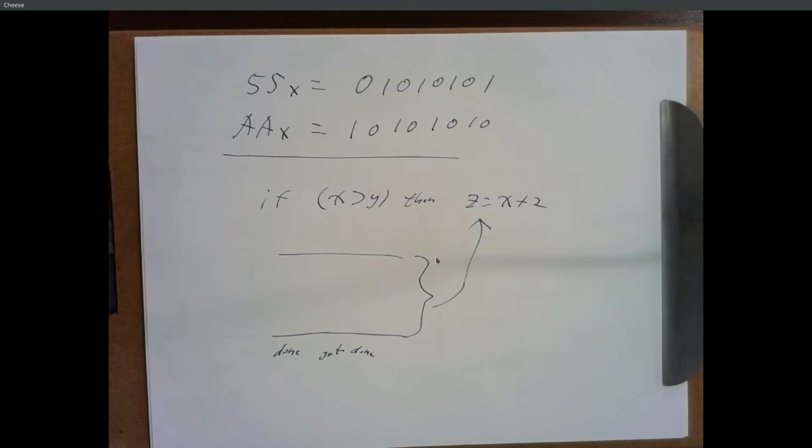You'll definitely see questions on the timers. So you want to know how to set up the timer configuration registers like T0CON, okay, for the prescaler, for do I want 8-bit or 16-bit and so on. And you want to know how to figure out what those settings should be for a given time interval. So if you want a 1-second delay and you know you've got 8,000 instructions per second, you need to wait for 8,000 ticks. If your prescaler is 1-to-1 and you're 16 bits, start at 65,536 minus 8,000.